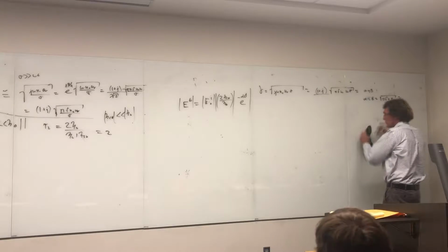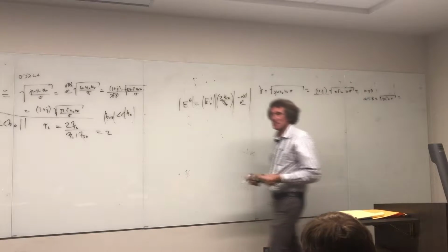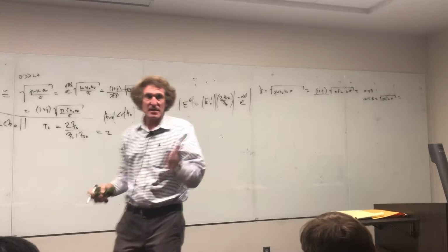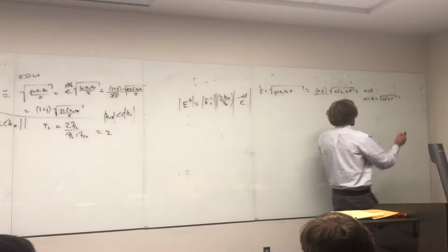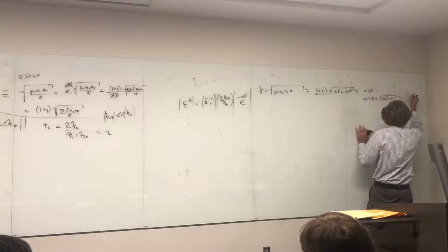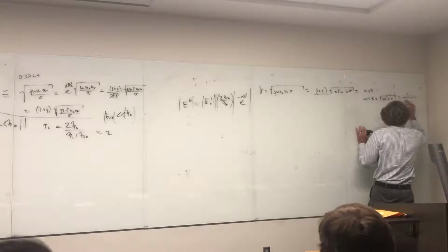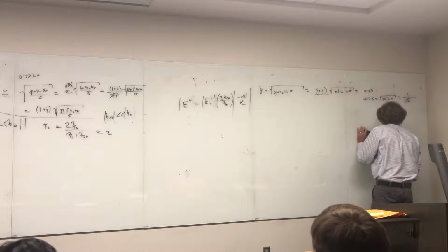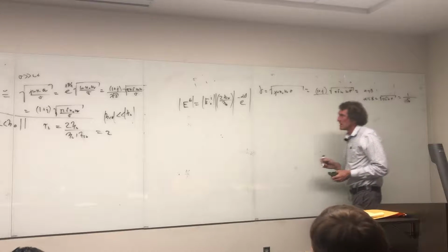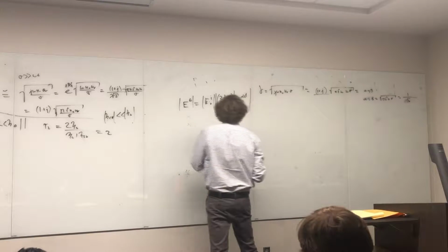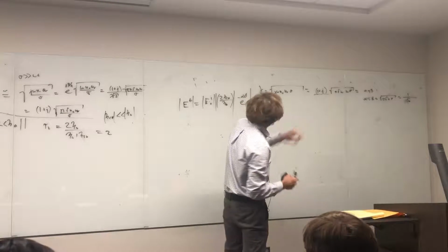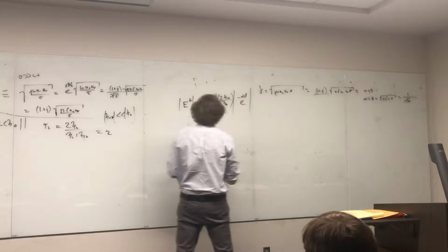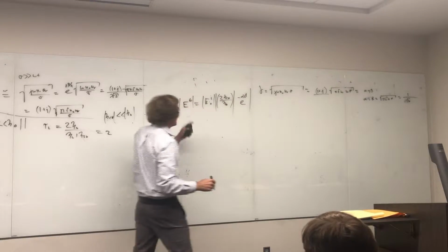Well, what is the square root of pi f mu sigma? Exactly, and 1 over the skin depth becomes a critical thing when you talk about shields. It's what the skin depth is. So this is really simply 1 over the skin depth, and that's the symbol for skin depth. So that means alpha here, I can put in as the square root of pi f mu sigma if I wanted to, and I will in a second, but this is the general form.